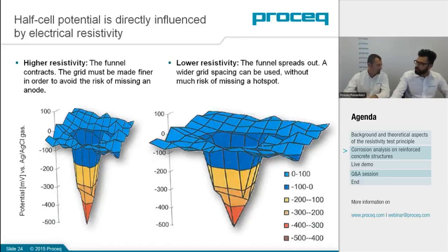Fantastic. You mentioned the recommended grid size based on the European standard. Is there a recommendation for the cover as well, just as a rough guide of what sort of cover we're dealing with? Well, typical covers that optimize that measurement range from 15 to 25 mm on a realistic structure, just to give some examples. Sure. Okay, fantastic.